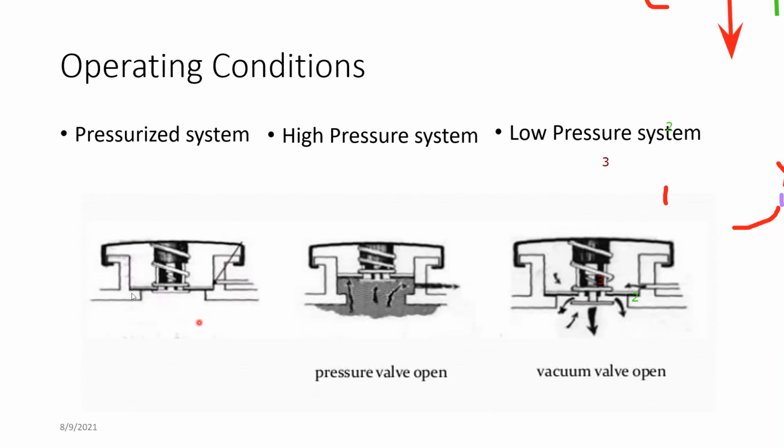Once you start again, the system has too much pressure. Again, this valve opens and sends the liquid out into your reservoir tank, right? So you fill the reservoir tank again. That is why you have a reservoir tank, and that is why the reservoir tank has high and low points. You should not fill over the high point.